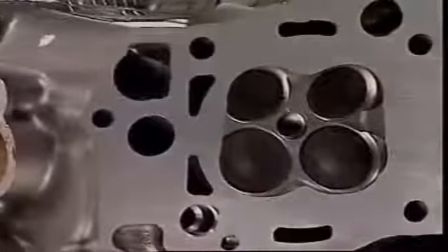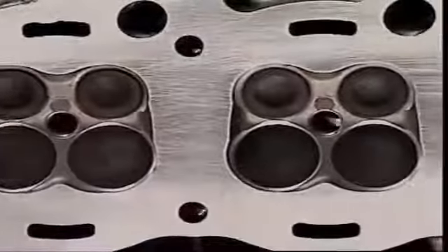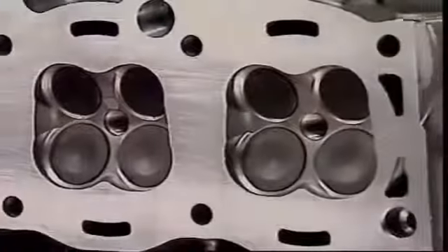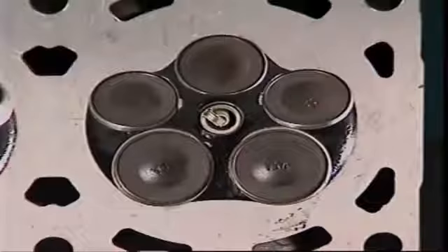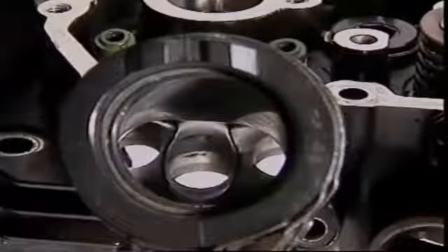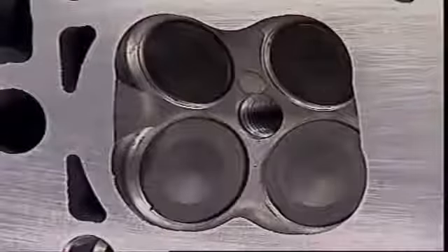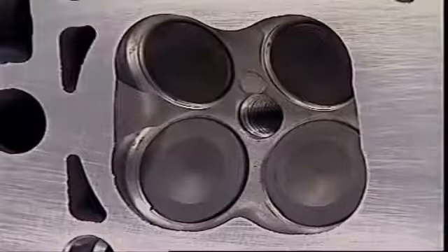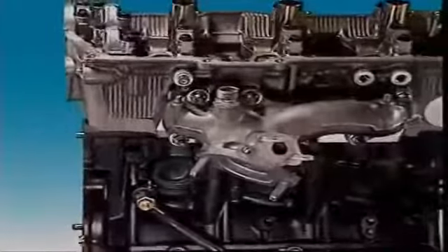Different engines use different valve combinations. Having more than one inlet valve provides better breathing. An additional inlet valve allows larger inlet passages and a freer flow into the cylinder, so the engine receives a better charge. Similarly, two exhaust valves mean the cylinder can be designed with larger exhaust ports, which provides a freer flow of exhaust gases out of the cylinder.